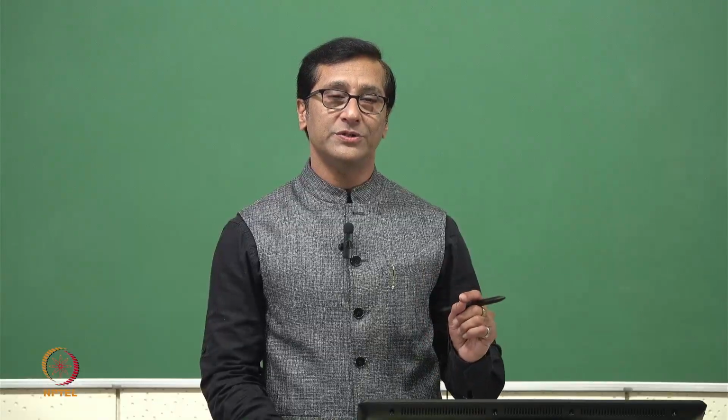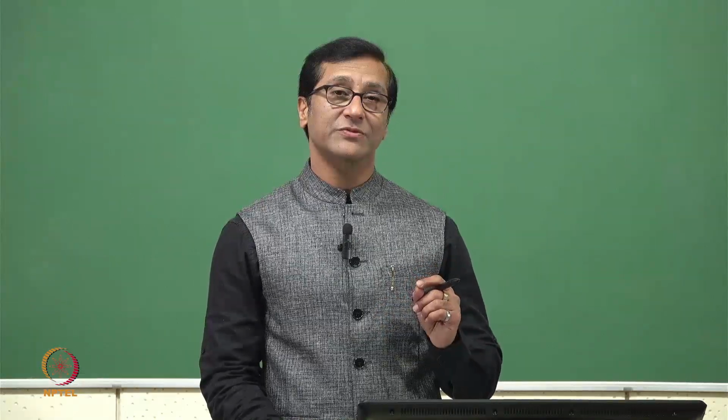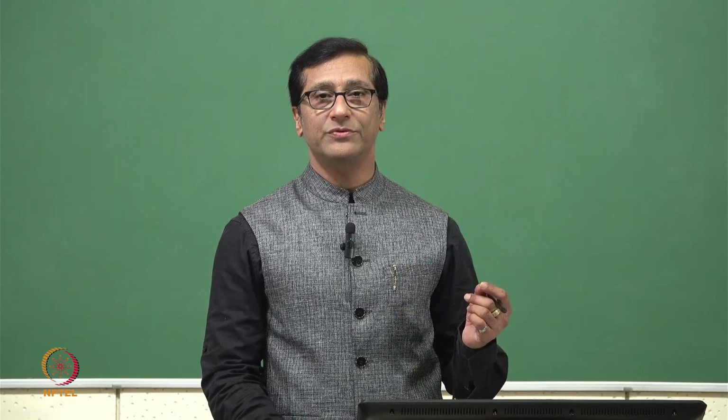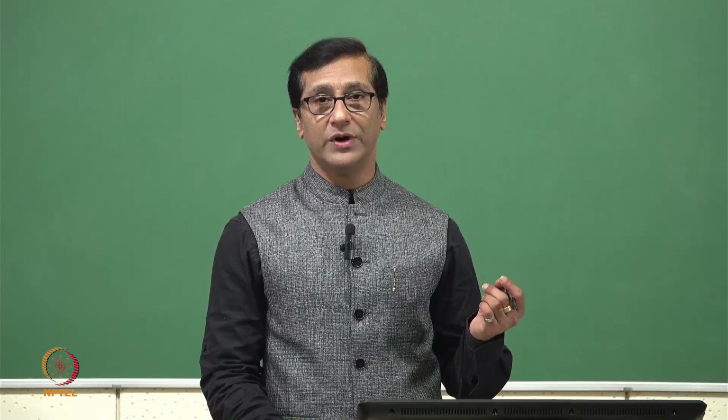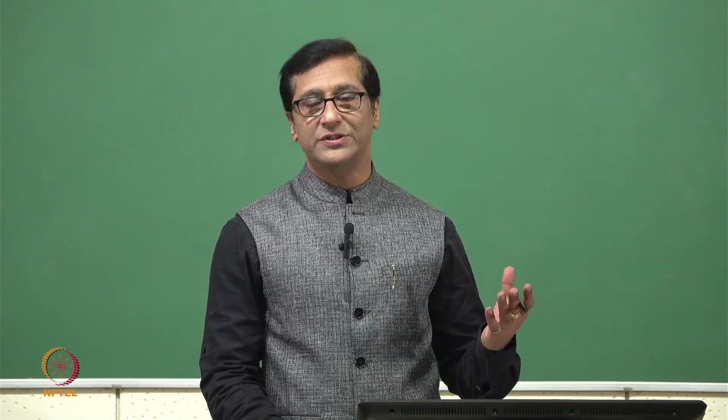Maybe in 90-95% of cases, after running in, surface roughness has improved, but quite possibly in some cases the surface roughness may get worse. Quite possibly, the initial surface roughness we keep at 0.2 micron becomes 0.5 micron after a few hundred hours of operation. Still, more or less running in really helps: it improves the surface quality, increases the conformity and adjustability between the surfaces, and will be really helpful to us.